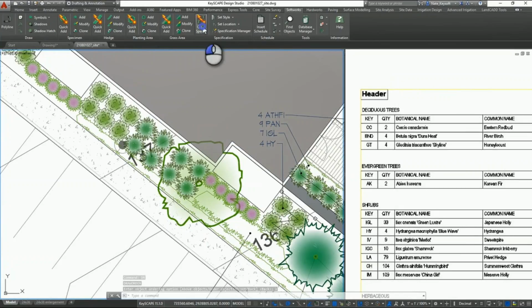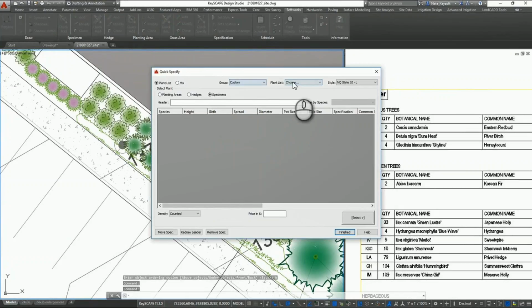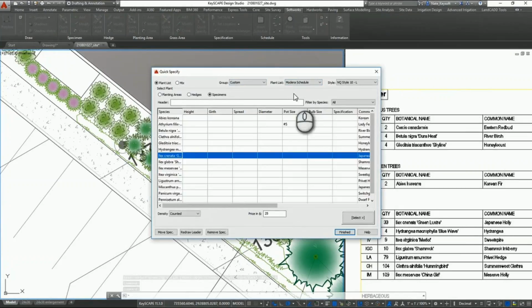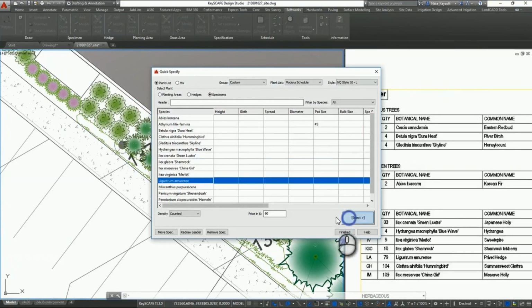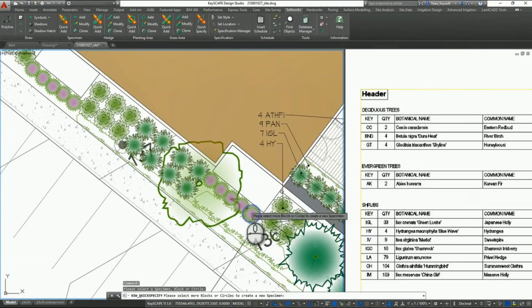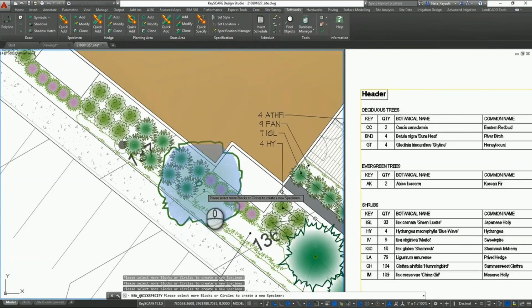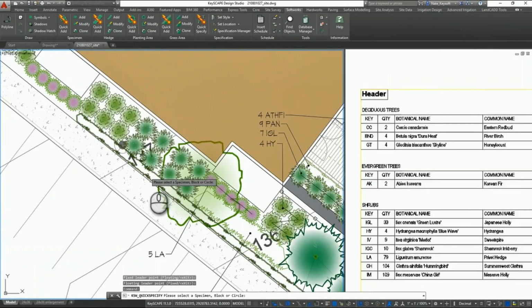We know that some are perennials, we know that some are evergreen or coniferous, some are woody plants, but now we're going to start assigning more specific data to it. So we know those 5 are ligustrum. And I can place this leader at this point. I don't even have to label it this time. I can just tag it with this information.